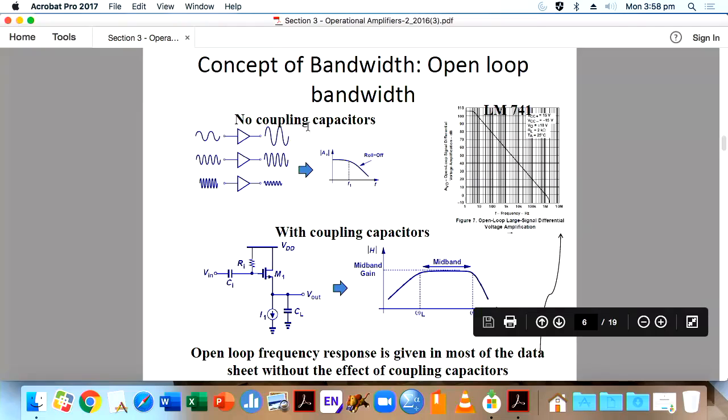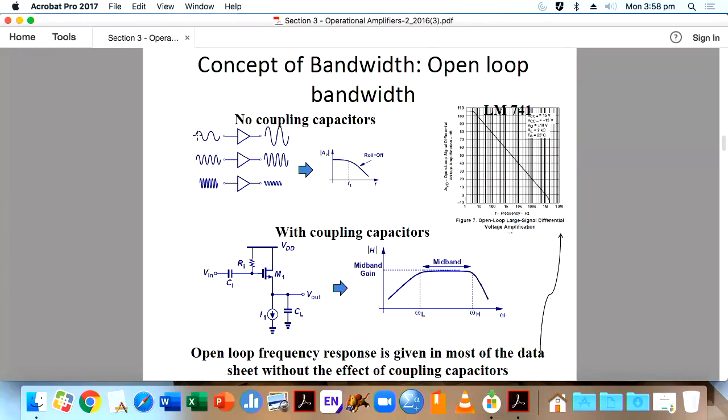You all know how to find the frequency response. For the frequency response in the ECD, you took the amplifier and connected a sinusoidal signal, and you kept the voltage at the input constant. Then you varied the frequency and found out the output. Then you plotted gain versus frequency. Have you done that one? You kept the input voltage constant, varied the frequency, found output by input, and then plotted like this.